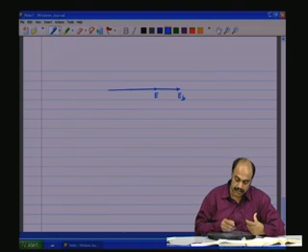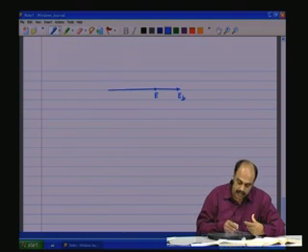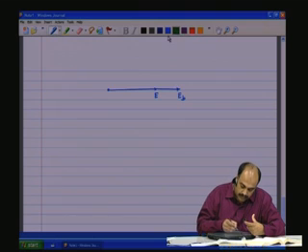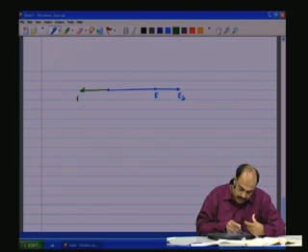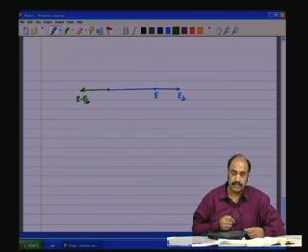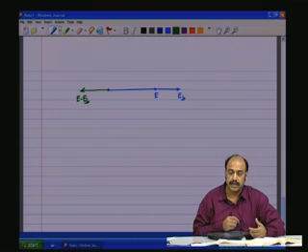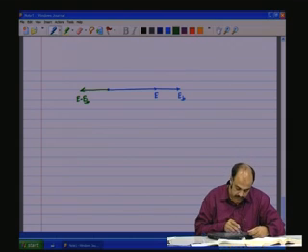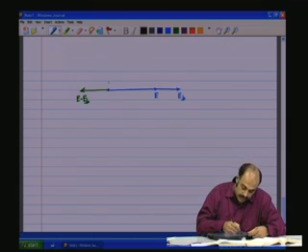E minus EB is going to be in the other direction like that. This is going to be E minus EB. Now the voltage across the synchronous reactance is going to lead the current by 90 degrees. Our current has to lag this voltage by 90 degrees, and that will be the direction of I.